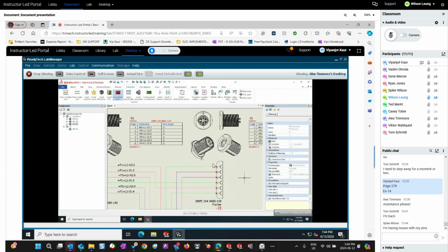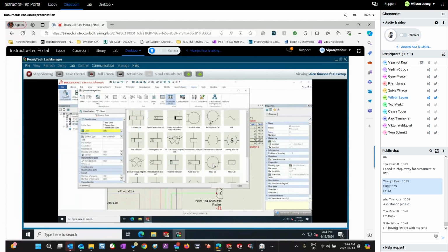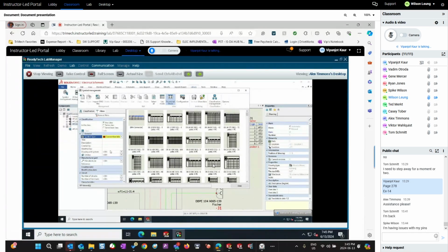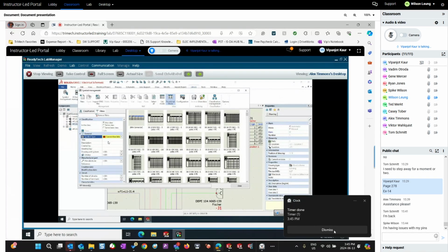Then you would say that VIP, where are connection labels stored in the library? So can you get to the library tab for me, please? So they're all stored under your first button, symbols manager. So connection label symbols, remove your filters, change your symbol type, fifth filter, symbol type, pick connection label. It should be the red color icon, scroll down right there. So there are so many connection label symbols that are stored for you. And you can download new ones from your content portal account.